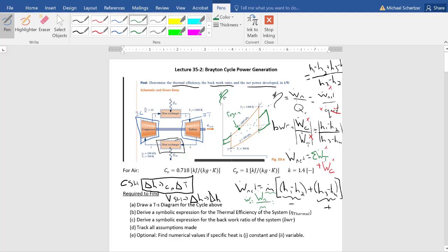So you have to think about the regenerator efficiency. That's going to be the actual amount of heat through the regenerator divided by Q dot max, which turns out to be, so the regenerator would get you from here, which if we were numbering these, 1, 2, 3, from 4 to 5.